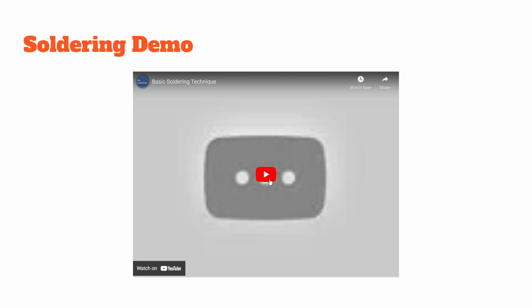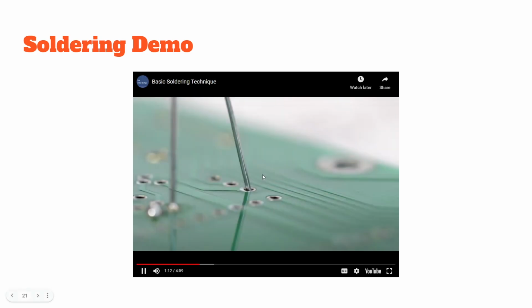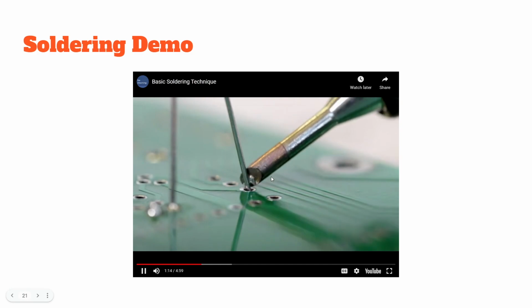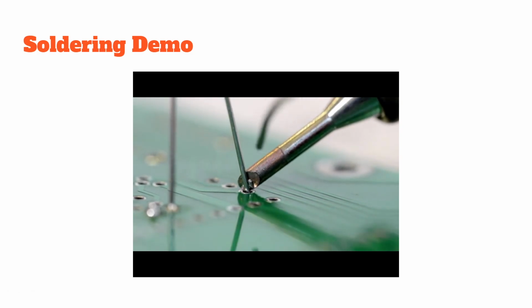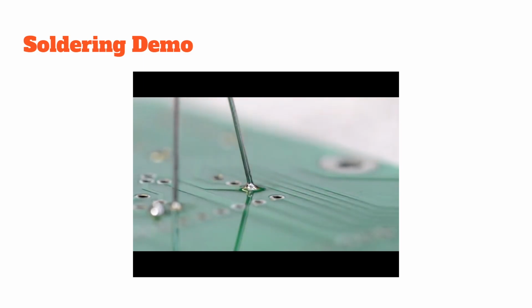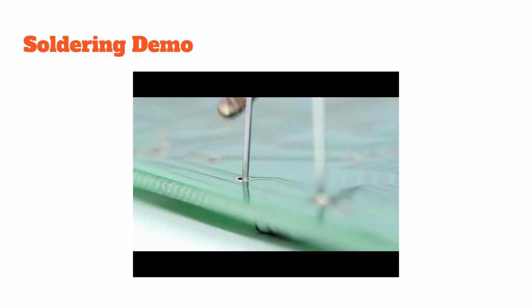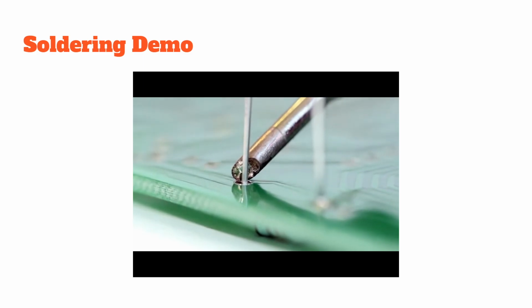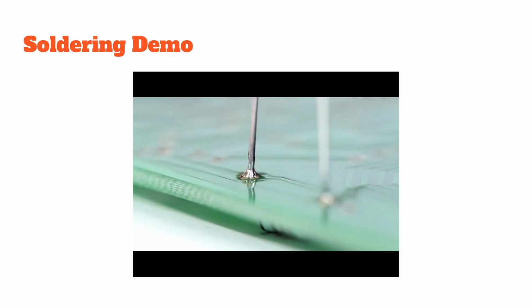yourself familiar with soldering. When it cools and solidifies, it fuses to the surface of a metal at the molecular level, providing good electrical conductivity between two metal surfaces. Solder normally contains flux, which helps the solder to flow, and also helps make a good contact by removing the oxides on the surface of the metals being joined.